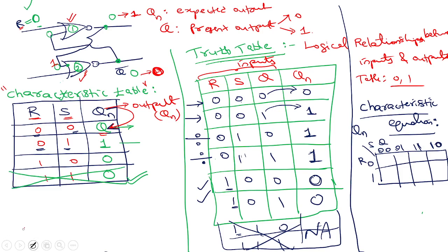So now let's see. Qn is 1 when 001 combination. Where is 001? Here. Then one more, 010. Where is 010? Here. Next, 011, here. Then 000 is 0, 100 is 0, 101 is also 0. What happened to the remaining two boxes? Any idea what to do?